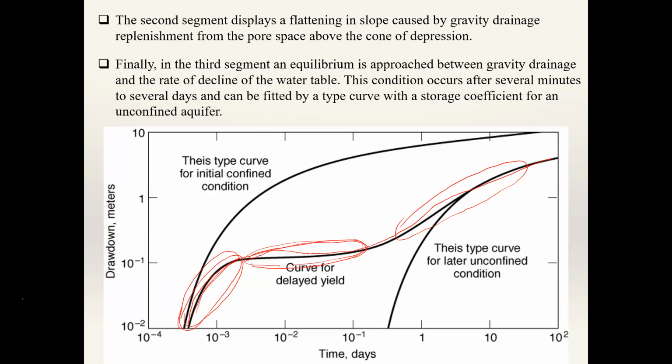Now you see the drawdown is insignificant, it becomes kind of flat, very small as time passes. The reason is that, in addition to the water coming from the saturated layer, water starts penetrating down from the unsaturated layer.